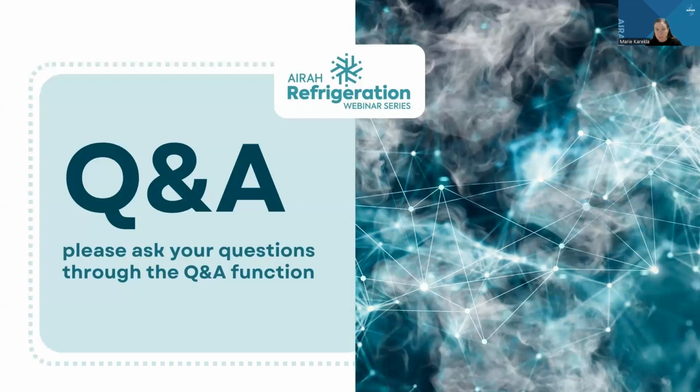Okay, so next one we've got here is, do you need to comply with AS 1668.2 for ventilation of occupied space? For unoccupied space, no. If it's occupied space, yes, you have to allow for it. Or the other thing is maybe use CO2 sensors to minimize the amount of outside air coming in.